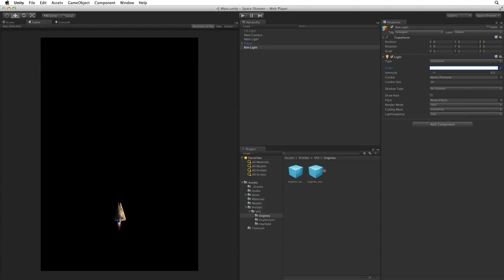Now, we want to light the rear of the ship in a way that complements the fill light. So let's rotate the light around to catch the rear edges of the ship, but on the same side as the fill. This looks good. Let's make this value a clean 65 degrees. This shows the edge well, but it's also acting now like a second fill light. This is mostly due to how much light spills onto the top of the ship.